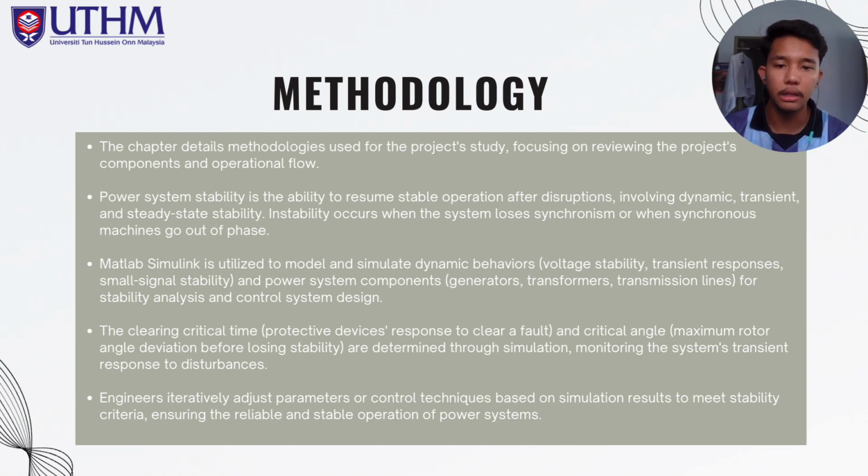The clearing critical time, which is the protective devices' response time to clear a fault, and critical angle, the maximum rotor angle deviation before losing stability, are determined through simulation, monitoring the system's transient response to disturbance. So engineers iteratively adjust parameters or control techniques based on simulation results to meet stability criteria, ensuring the reliable and stable operation of the power system.